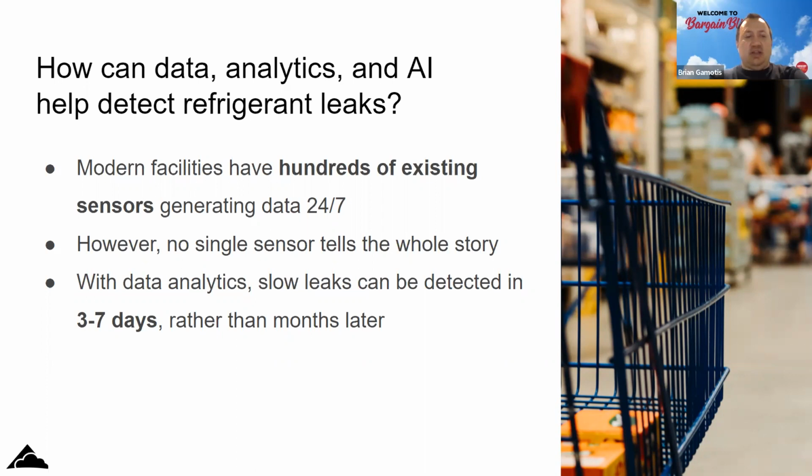If you can catch a leak early, the split is the perfect example. Every spring as a tech, you ended up with a steady stream of service calls for low liquid on all those systems that sat in split condenser all winter long with a leak. Then they come out of split in the spring and all of a sudden they don't have enough gas in them.